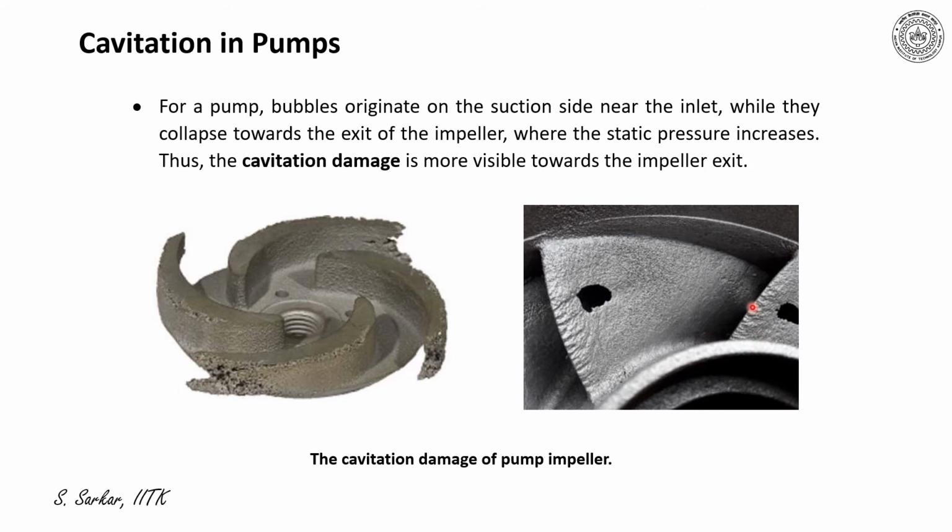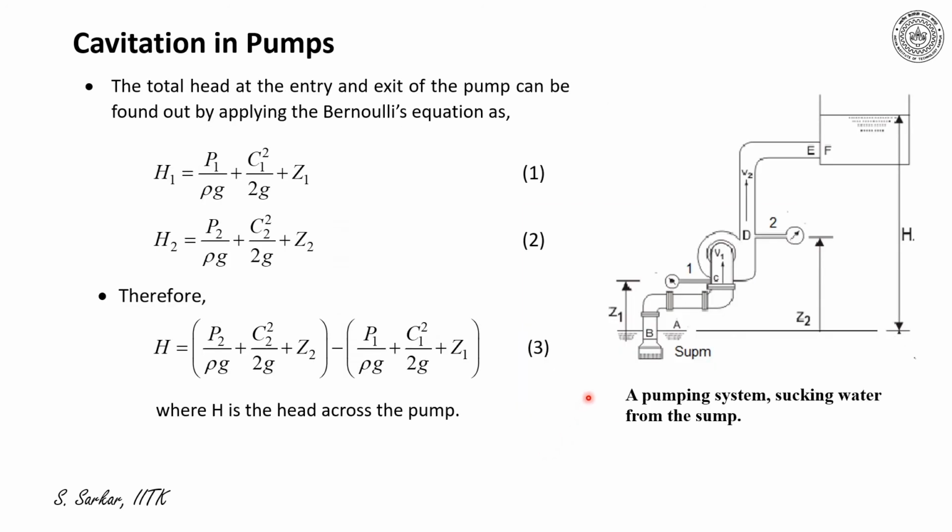Furthermore, if you take a mixed flow pump, you'll realize although the bubble is originating on the suction surface near inlet, the significant damage occurs at the exit of the impeller. I have presented here the schematic of a pumping system along with the sump and the reservoir.